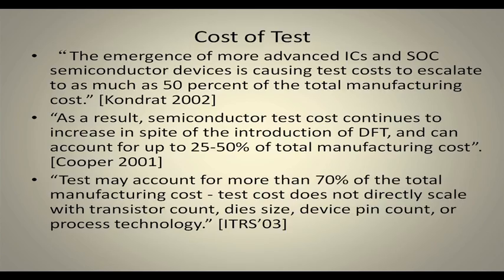For VLSI chip design and manufacture, we have two costs. One is the non-recurring engineering cost, which is the design part of it, and then per unit we have some cost. Since we are doing this in a massively parallel way, a large number of chips are manufactured simultaneously. So, the non-recurring engineering cost is high, but the unit cost is low. That way the overall cost comes down when we manufacture them in large volume. So, the designers are happy with producing more and more chips with the same design. However, each of these chips that are produced has to be tested.